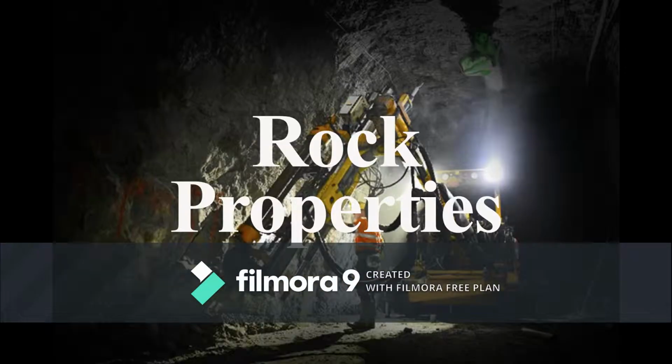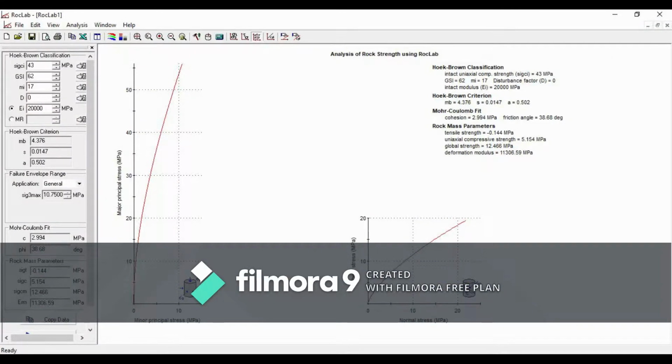So, beginning with our first part, in this section we will try to find different rock properties of sandstone, which is our roof, and the limestone. For this reason, we have used the RockLab software to calculate the rock mass properties of limestone and sandstone. Here is the software RockLab, in which you can enter your data input and get your results, that is, the rock mass properties.